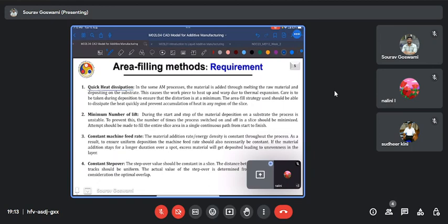For example, in DED, the laser heads can have power that go from say anywhere between 3 to 8 kilowatts, and this gives rise to a very high heat input. So that heat needs to be dissipated, and we know that it is the thermal gradients and the transfer of heat which actually governs the microstructure's evolution, the solidification characteristics of the finished part.